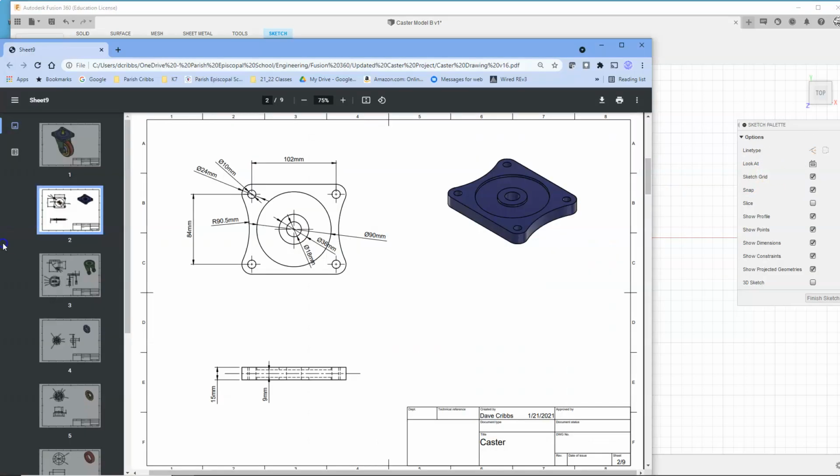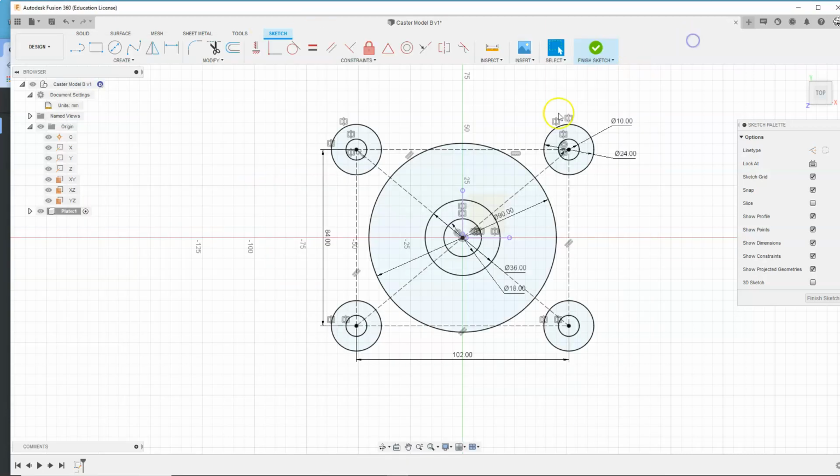So now on top, I just have a straight line going across the top and bottom. So we'll add those in. Come up here to the line command. And it's going to snap to the circle. It's kind of hard to get it perfectly on top. So I'm just going to go ahead and miss kind of big. I'm not even going to get anywhere close to the top. I'm going to get on the inside.